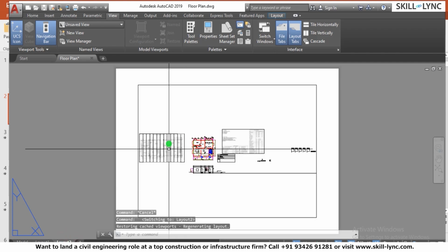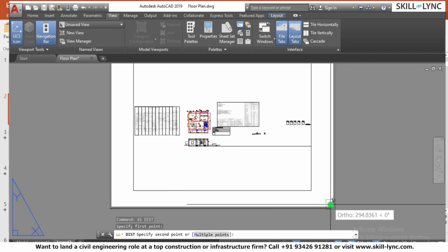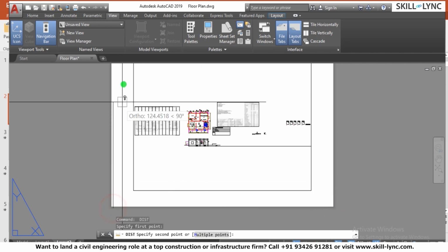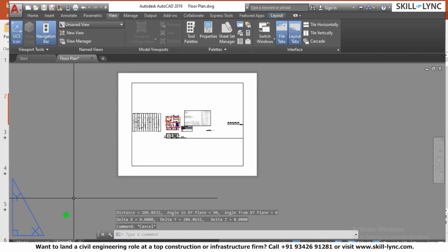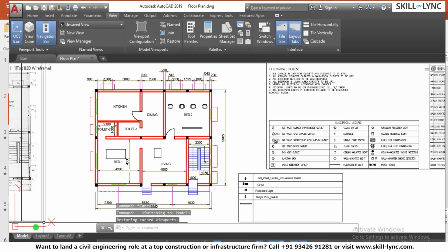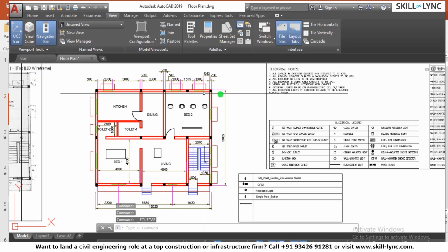Similarly, if you go to layout 2, you can also measure it. So we can have different page setups. For example, it's the same. So this page is an A4 paper size. So we will be creating more pages, paper sizes, and putting them into the layout. Now let's see how we will be starting out with the layouts. So if these layout tabs are not visible, here you can see the layout tabs, you can put it off, the file tabs. So file tabs is this one.